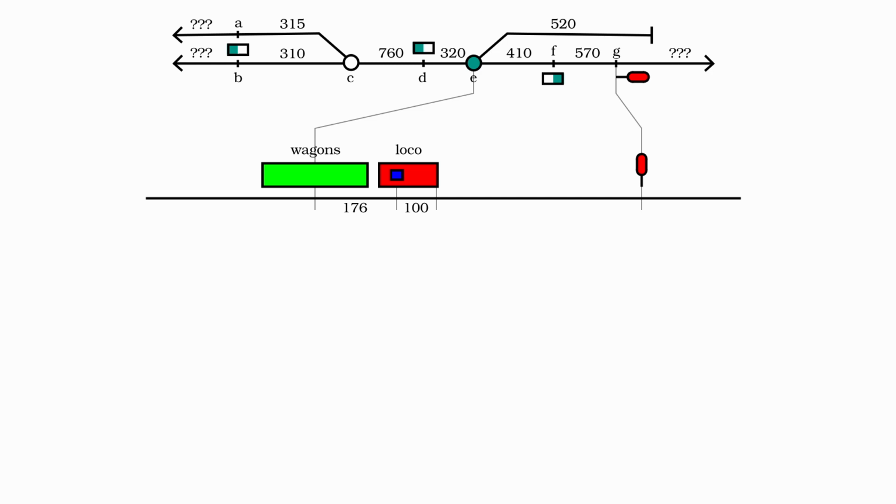When the code decoder was installed, you told the system that the length from the code decoder to the front of the locomotive was 100 mm. The system also knows that the signal named G is 570 mm after the magnet named F, and therefore the distance from the magnet named E to the signal is 980 mm. The distance to go is therefore 704 mm.